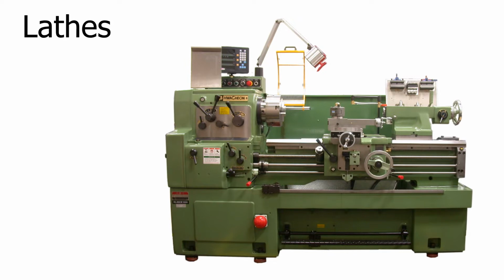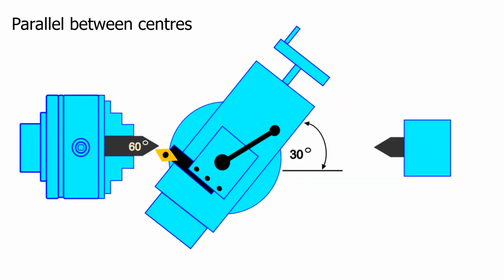The first machine tool we're going to look at is the center lathe. Here, I will be checking to make sure that when turning between centers, my job is parallel. I am not the only user of this lathe, and I'm not sure what has been set or unset by the previous operator. I will be turning a hydraulic push rod and it needs to be parallel.